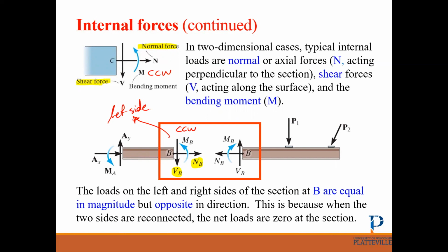If this one is clockwise, this one is counterclockwise. If the shear is going down for this part, it's going up for this one. And the normal force is always going outside. But the most important things in design are shear and moment, more important than finding normal force. So usually we just focus on finding shear and moment diagrams. That is something we need to learn later on.